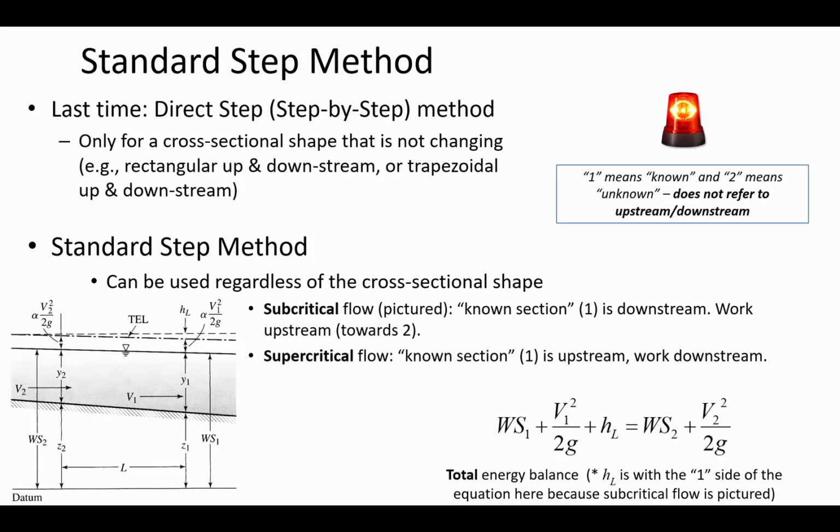And it uses the standard step method to predict what will be the flow depth at different cross sections in that channel. So we're going to look at the theory behind the standard step method before we get into the particulars and the calculation process that's in that spreadsheet template that I emailed you earlier today.